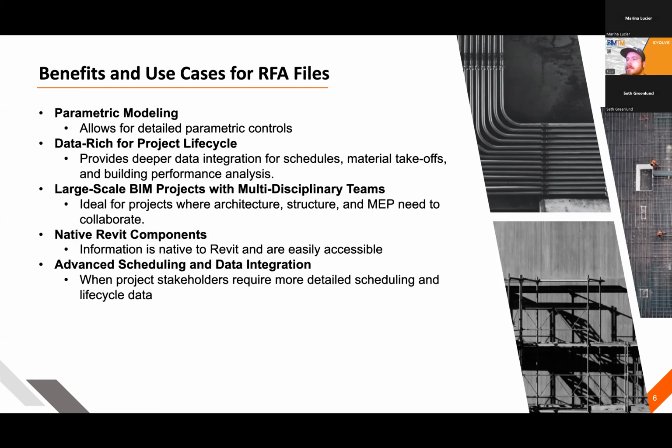If you think back to the AutoCAD days, you would XREF things in, but you didn't necessarily have full access to what objects were in the XREF items. So linked models are hugely powerful with Revit in general. And then also the ability to work share allows multiple people across multiple disciplines to all be working on a project at the same time. Again, just a much better collaboration experience.